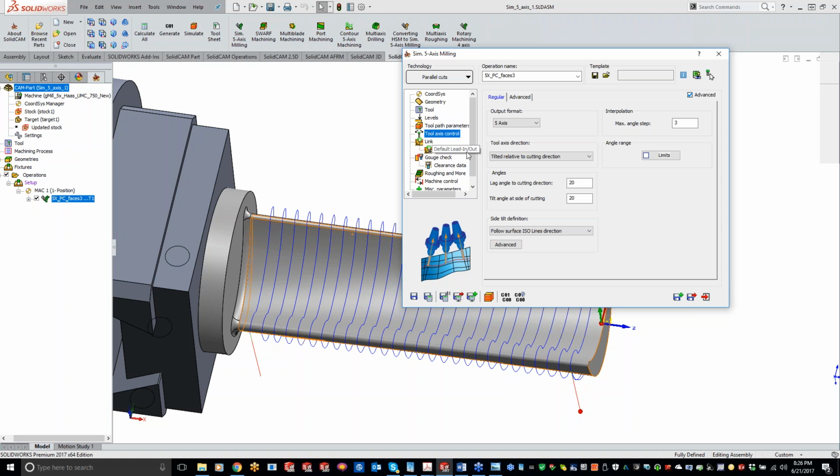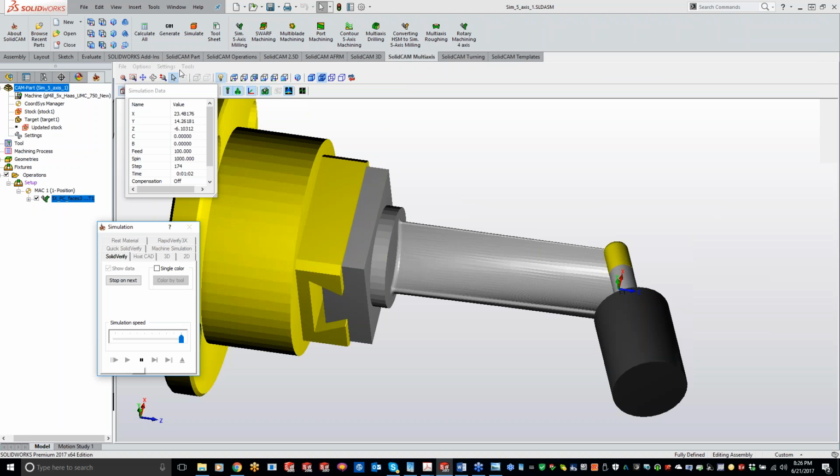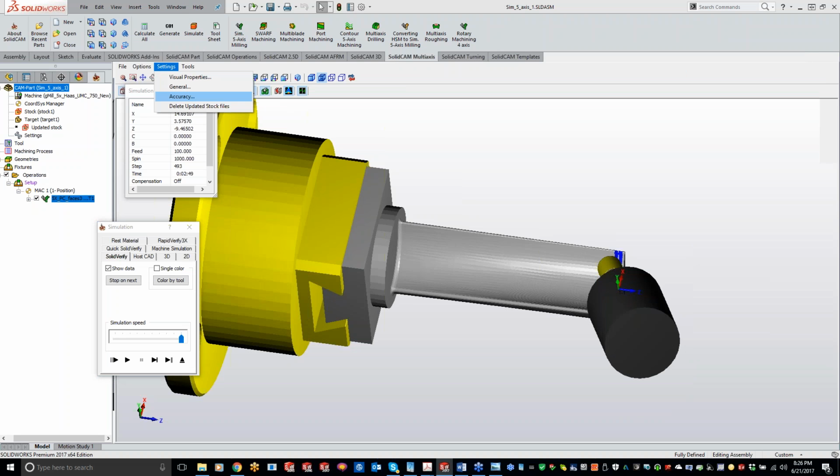Yep. Now on our last part here, we're going to get really deep into the gouge checking side of things, just because we're going to be doing basically, well, I'll just wait till we get to that point. So now that I kicked that side angle over at 20 degrees, you'll see that I was able to get my toolpath a little bit closer in there, to get more of that material out of there. Let me just pause this for a second. Let's go to my general here and let's bump this up so you guys aren't waiting.